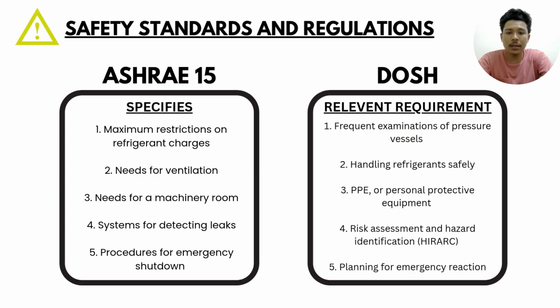To address this hazard, our system must strictly comply with both international and local safety standards. Globally, we follow ISO 5149, which dictates strict limits on refrigerant charge and mandates proper ventilation, dedicated machinery rooms, leak detection, and emergency shutdown systems. Locally, for our Melaka plant, we must meet DOSH requirements.